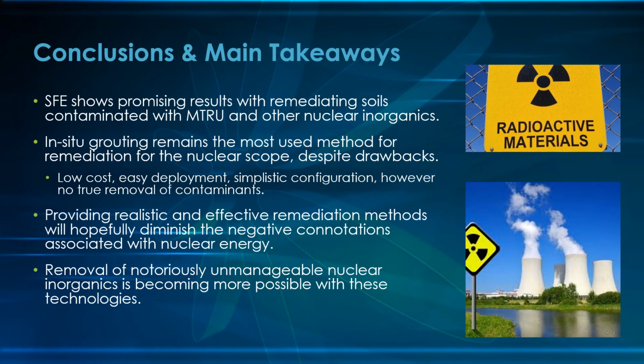Some of the conclusions and main takeaways I hope to provide people with this presentation and my report are, first, SFE shows promising results with remediating soils contaminated with MTRU and other nuclear inorganics. However, in situ grouting still remains the most used method just because of its simplicity, its low cost, and its easy deployment. But we're still not getting that true removal of contaminants, which we really want to start accepting now. So if cost optimization does happen for SFE in the future, we should start to see that take over in situ grouting as the most common remediation method.